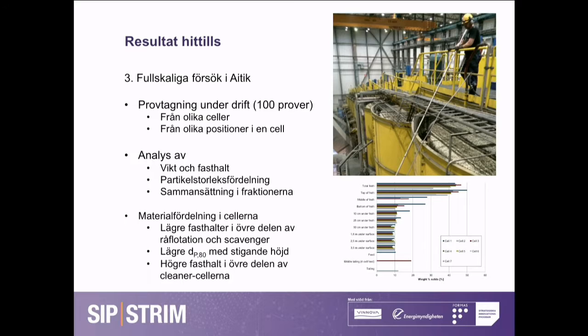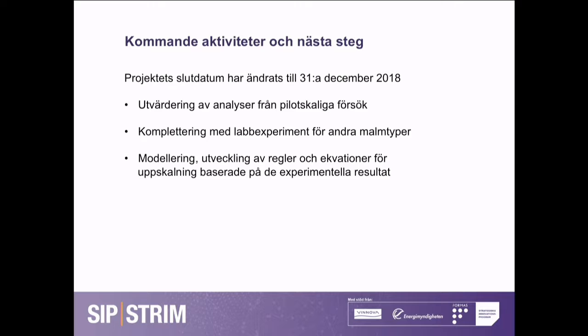We, in that case, did a campaign with over 100 samples from different cells, so from rougher, scavenger and cleaner flotation. And we looked at these vertical profiles, as you see in the lower right corner. So looking at the distribution of solid material, the composition at different levels, and also particle properties.